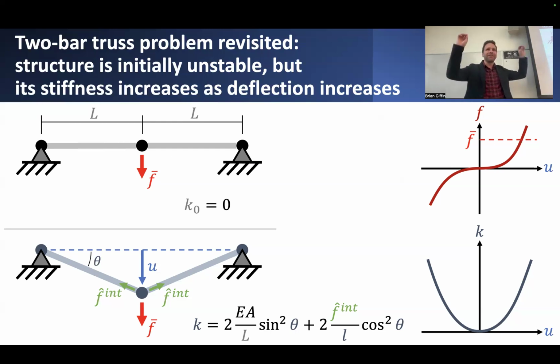Technically speaking, when you have a cable that has no tension in it and you're trying to deform it transversely, when you first start to deform it, it will have 0 resistance to that transverse motion. So there should be no stiffness associated with that. But as soon as you start to deflect this cable transversely, something starts to happen, particularly if you're holding the endpoints fixed. What happens?